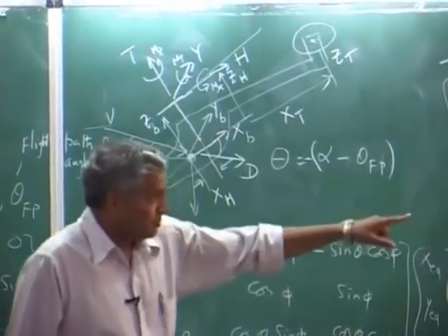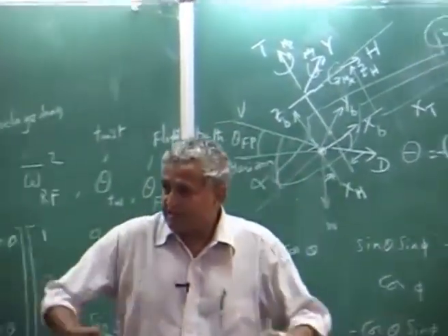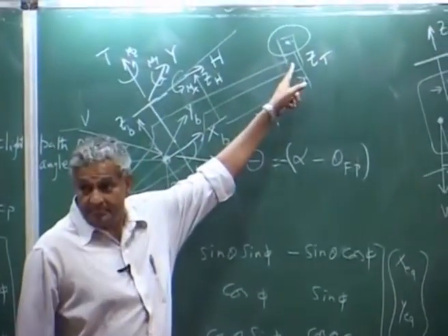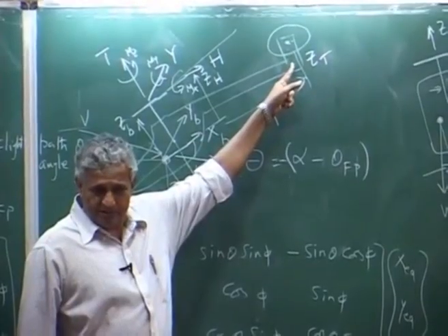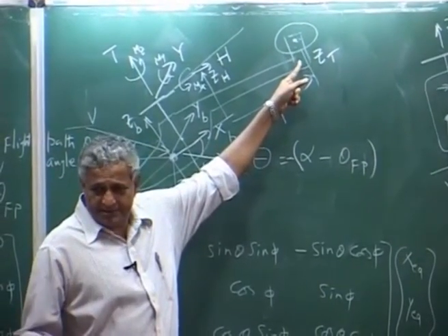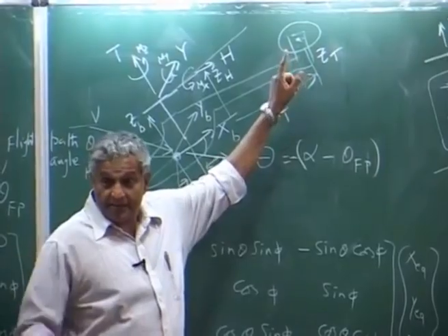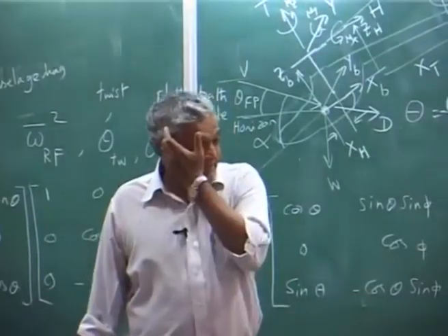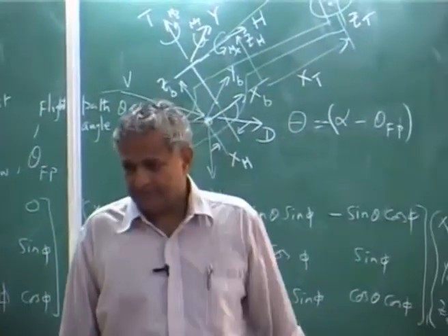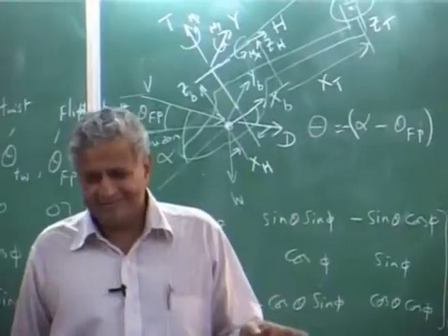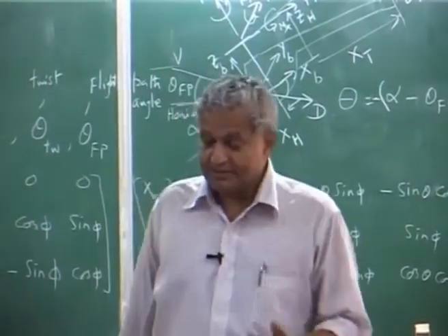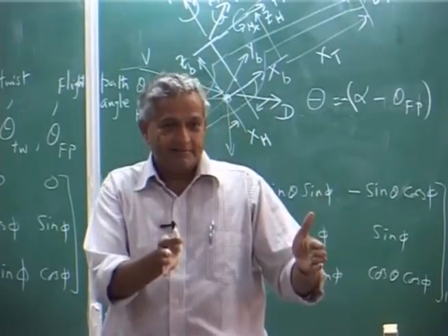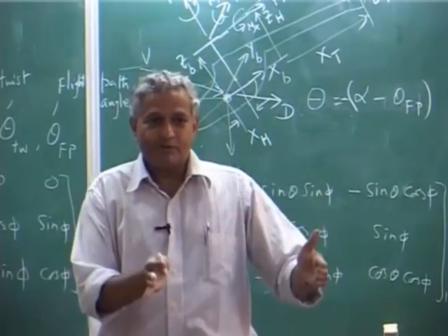Now, you see in the pitch moment, I do not have any horizontal surface. If I put a horizontal surface here, like a small aerodynamic surface, a flat plate kept at an angle, that will give a pitching moment. Usually big helicopters have that. If it is a small weight class, they do not, but sometimes you will find some helicopters have only half of the tail, not on both sides.